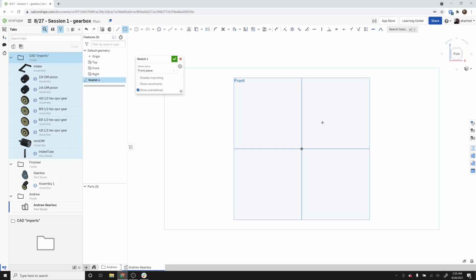If you do a rectangle, or any part, when you are making your sketch, you'll see that some things will turn orange, and that is if you're getting a constraint somewhere. In this case, I get an icon that is a horizontal line because it is going to constrain it to being horizontal to the origin. Or I can move up here and it is going to constrain it to being vertical to the origin. Or if I go here, this is called coincident, and you can see it even gives me a box around it. Basically, coincident just means on top of.